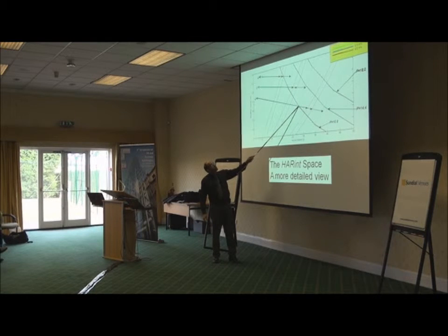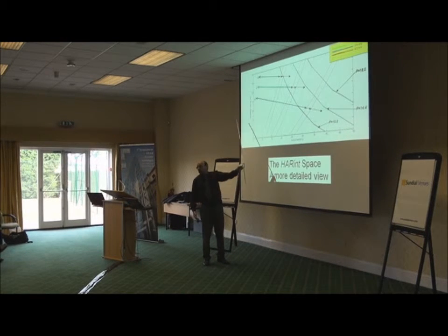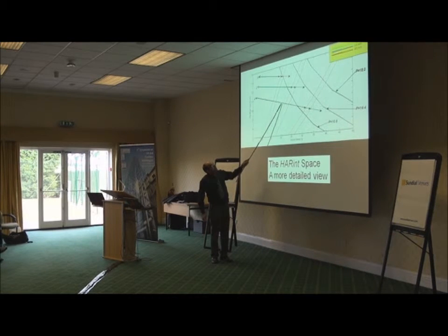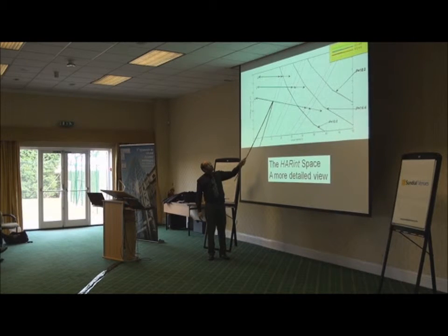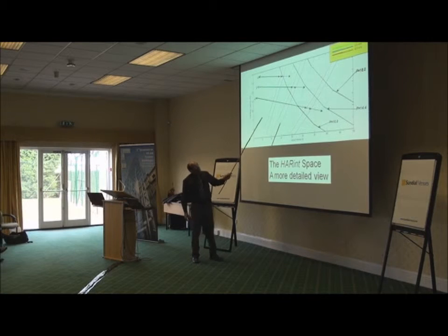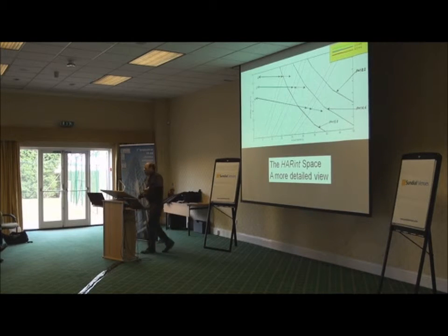So you go 5 lifts at the lowest speed, 5 lifts at the medium speed, 5 lifts at the high speed. To go further, notice we're moving this way towards better solutions. As we increase speed and number of lifts, we move towards the optimum. Then we have to increase the number of lifts. So we go to 6 at low speed, 6 at medium speed, 6 at high speed. We haven't said anything yet about average traveling time, average waiting time.